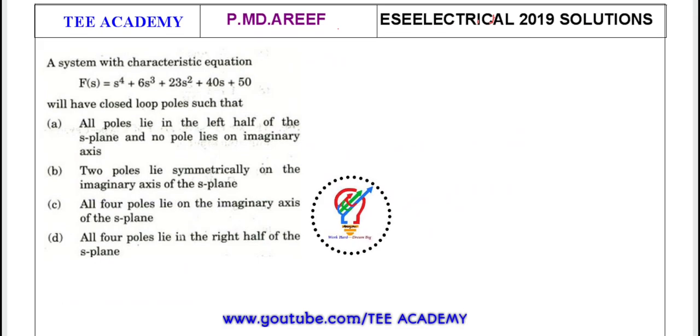A system with characteristic equation f(s) = s⁴ + 6s³ + 23s² + 40s + 50 will have closed loop poles such that: all the poles lie in the left half of the s-plane and no pole lies on the imaginary axis; two poles lie symmetrically on the imaginary axis of the s-plane; all four poles lie on the imaginary axis of the s-plane; or all four poles lie in the right half of the s-plane. To get this answer, first we will take the help of the RH tabulation.